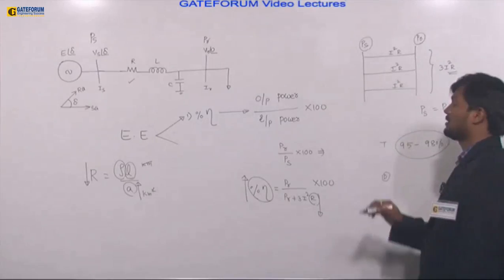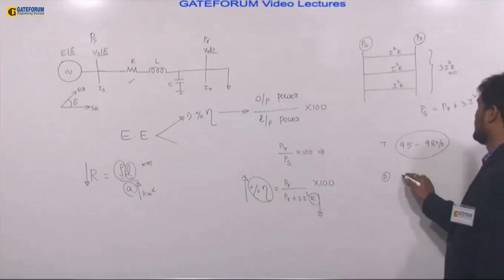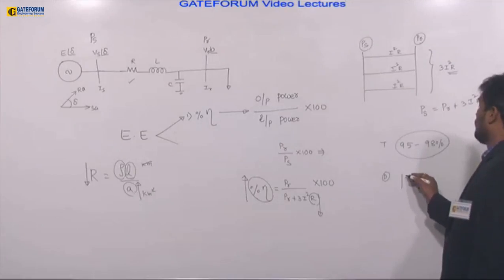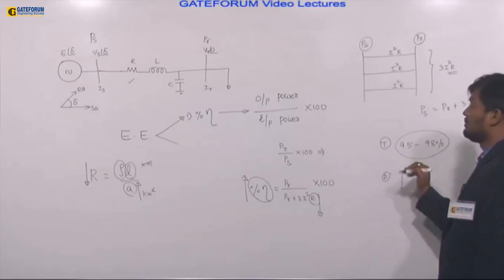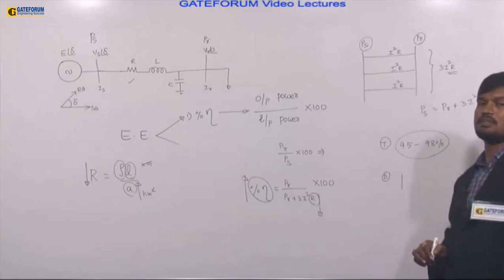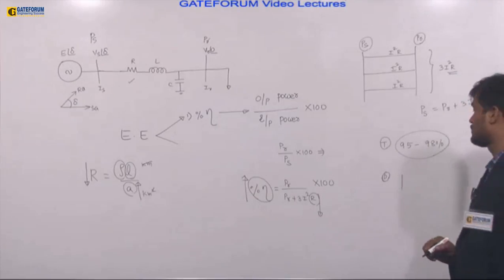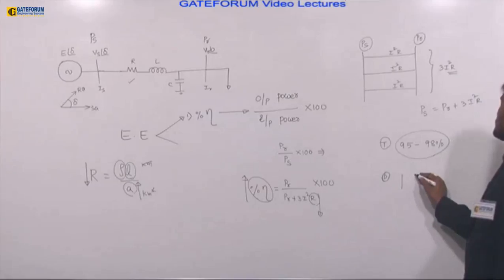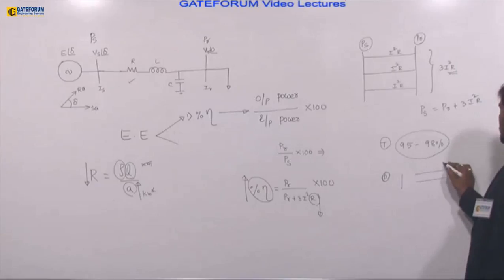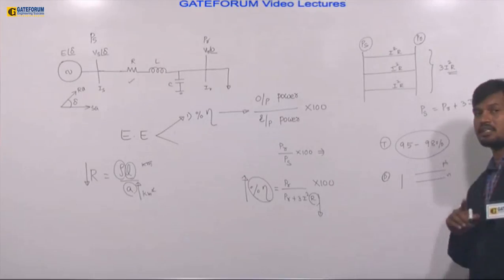Next, distribution lines are also there. In the distribution system, see, are losses more in distribution or transmission? It is one of the interview questions. Definitely the answer is that distribution system losses are more compared to the transmission system. Reason: in the distribution system there is a phase, there is a neutral in your street.